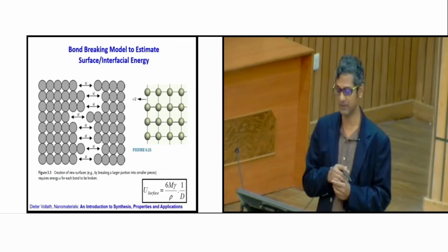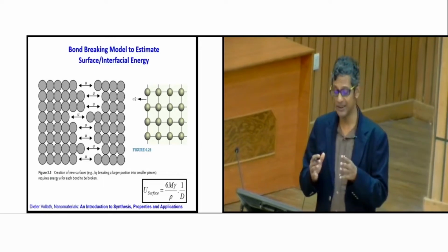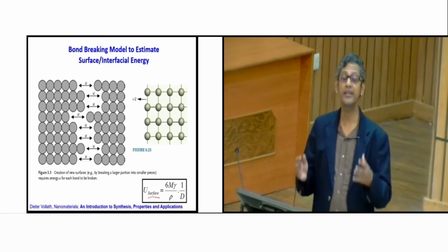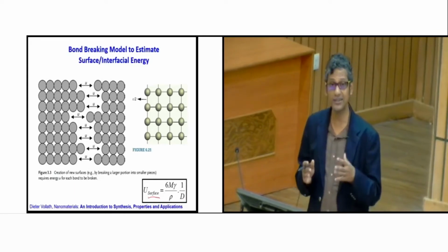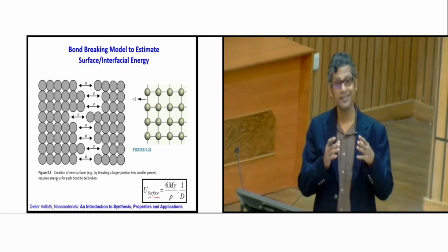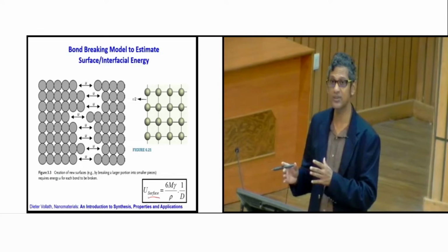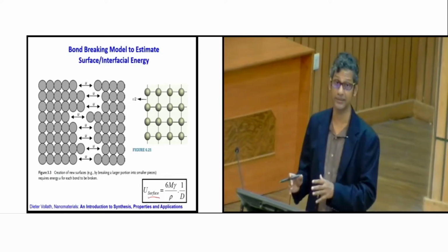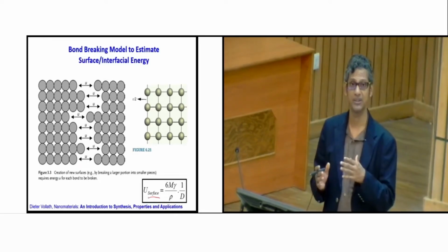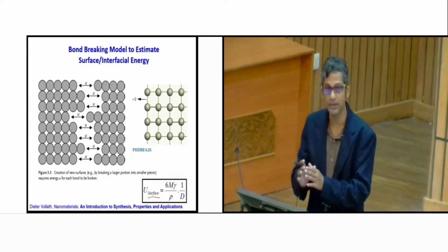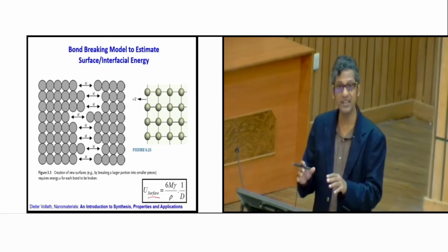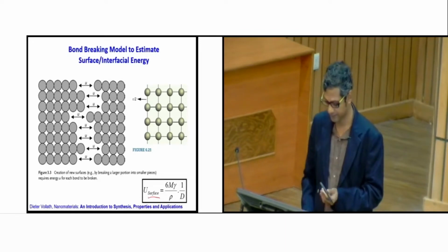That's the critical aspect, okay? As you decrease the size, U surface increases. You see, U surface will increase at a very high rate as you decrease the size. That's an important aspect. Not only does size reduction lead to an increase of surface energy, but it scales with the size. Therefore, we need to understand how it scales with different kinds of shapes. It is only true for the spherical one, but what will happen if you have a cuboid, or a cone, or a cylinder? That's something we'll discuss today.